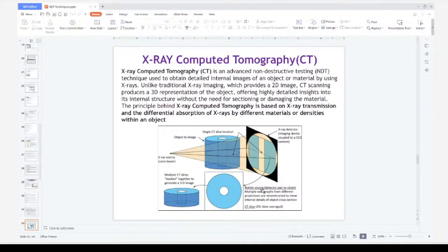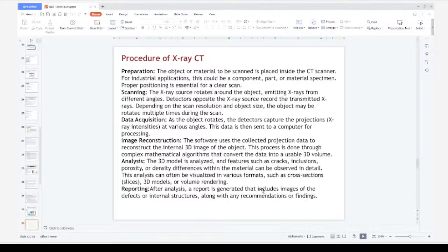That's all that's happening. So it is not a passive technique. It's more of an active one, where you send some external stimuli, the defects respond to that stimuli, and that stimuli will be captured by the sensors. It needs sophisticated computer algorithms to get these signals, convert them to electrical signals and make them interpretable. So it's mainly used in heat exchangers or the nuclear industries, where I need online inspection. And corrosion is a thing which can be easily detected through acoustic emission.